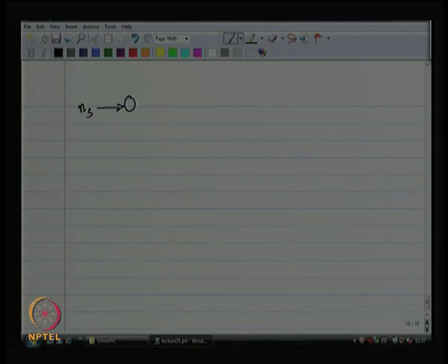What I am going to make sure is that the extra noise that I add, because I have the low noise amplifier, because I have an amplifier I am going to have some extra noise, right. That extra noise is equal to or smaller than, or not a large fraction of, the noise existing in the signal. So, N1 and Ns should be comparable, probably N1 should be lesser than Ns, N1 should be as small as possible. Basically, this is what a low noise amplifier means.